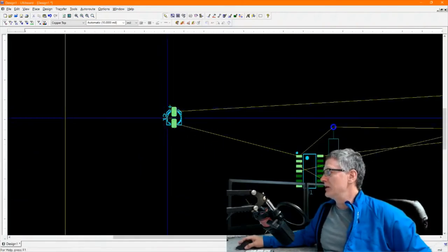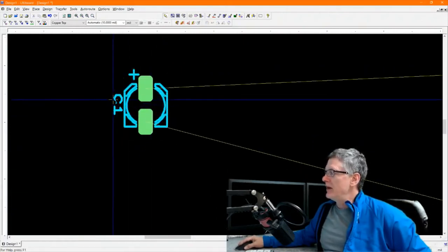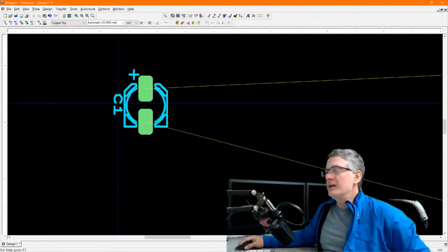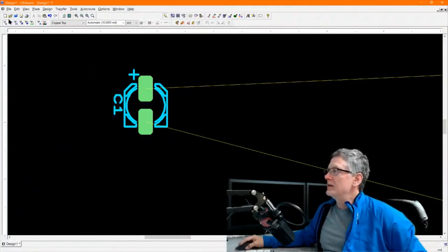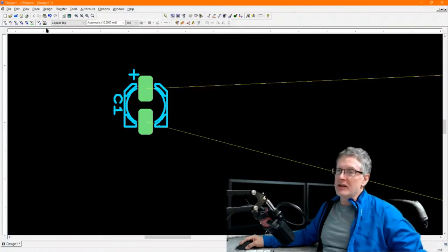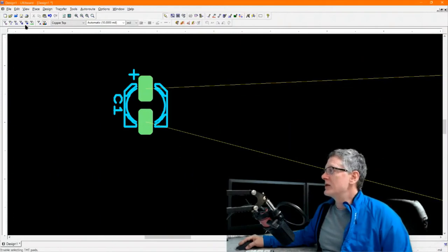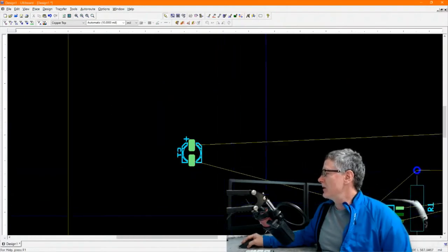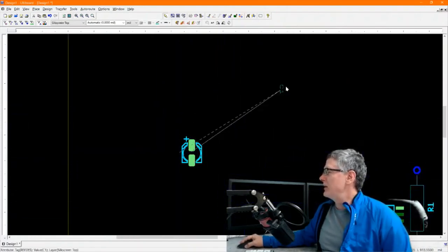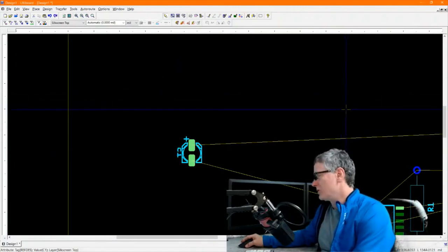You can zoom in here on this object. This is the capacitor. You can grab the name separately and move it around. Right now I can't. And the reason for that is if you go up here in the corner and look at these, now your menus might be in a different place. You can turn selection enable on and off for different object types. It's kind of frustrating when you're trying to do something and you come over here to grab this capacitor and you grab the name and you just move the name around, and then you go, Control Z will undo it.